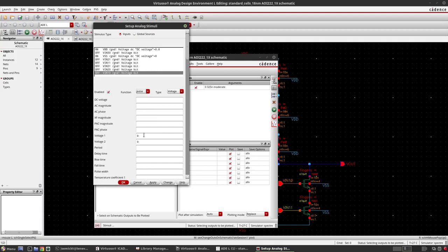So pulse I will give, and voltage 1 I will give as 0.8. Okay, and voltage 2 is my 0, and period will be 10 nano. Then delay rise time I will keep 50 pico, fall time also 50 pico, pulse width I will give as 5 nano, and I won't be providing any delay time, and I'll just click on apply. Similarly I'll do it for V11.